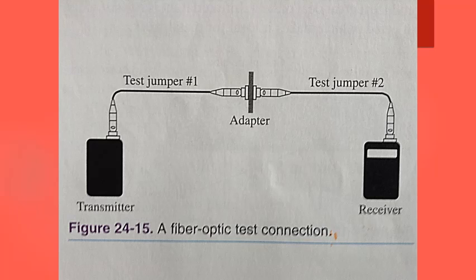The vertical drops indicate the losses at the splices or connectors. The signature trace can be stored or connected to a computer to print a hard copy of test results. And looking at figure 24-16 again, it is a signature trace of a fiber optic system, which could be an example of a printout of a test for signal loss for a fiber optic cable.